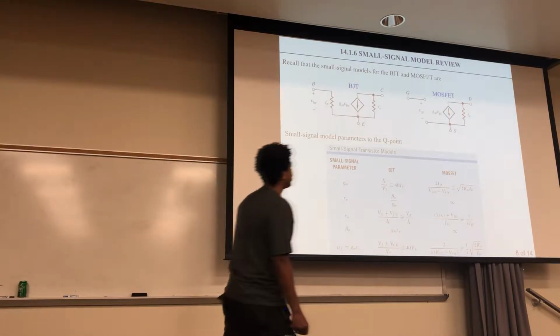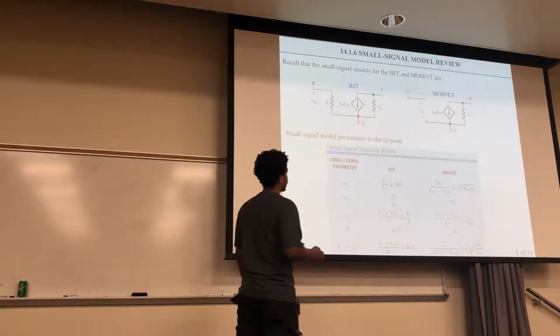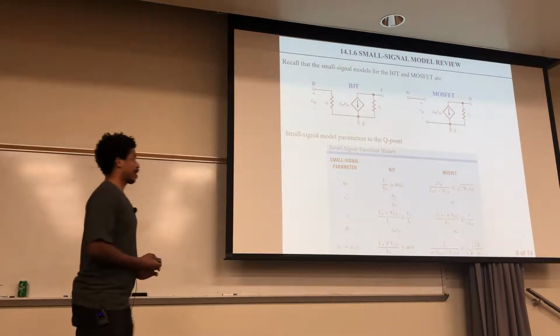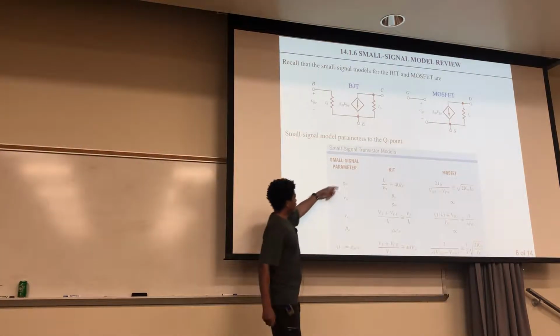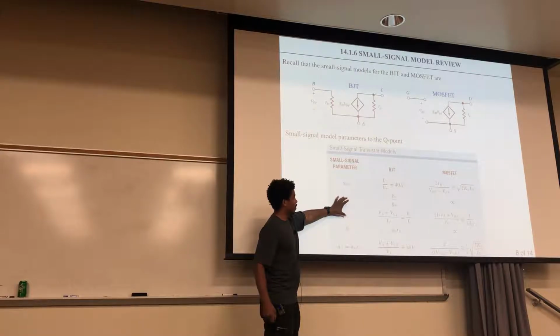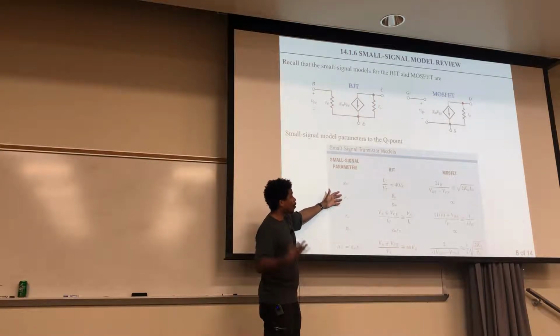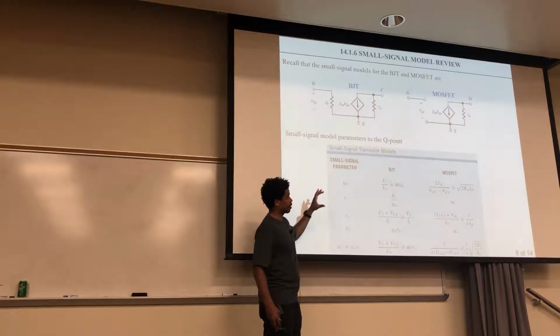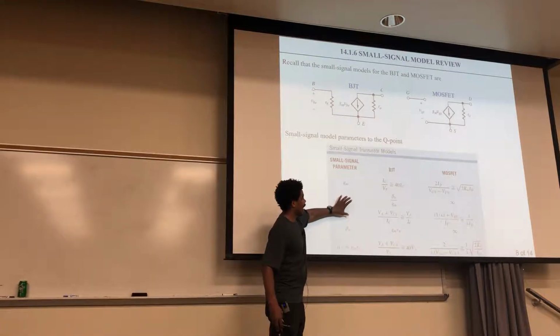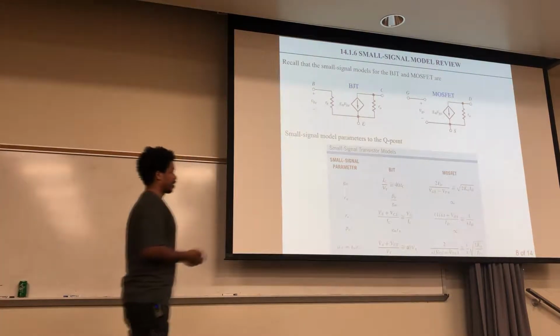And also, well, there are pros and cons, and we went through a lot of these. Oh yeah, but keep in mind, this input resistance and this output resistance correspond to the transistor only, not to the other resistors that surround them. So if you want to find the overall input and overall output, you have to look from whatever input you're considering as input and whatever output you're considering as output. Okay, but this R pi and R0, that's just for around the transistor itself.